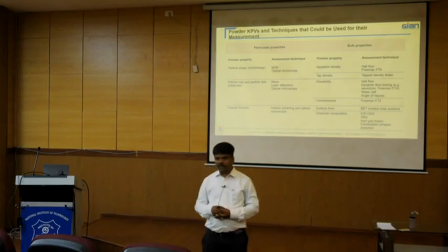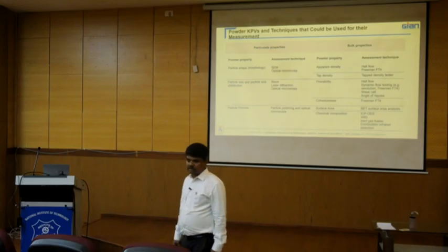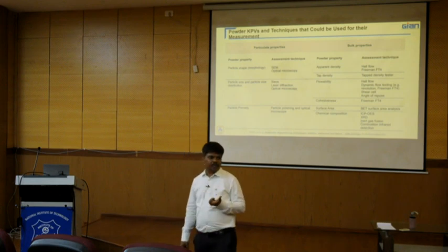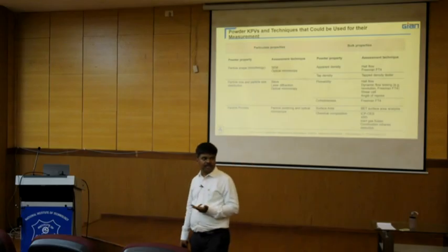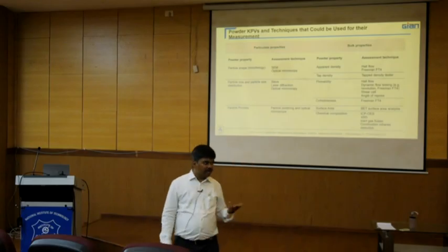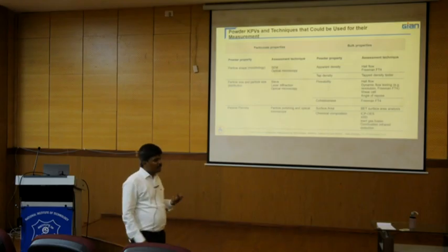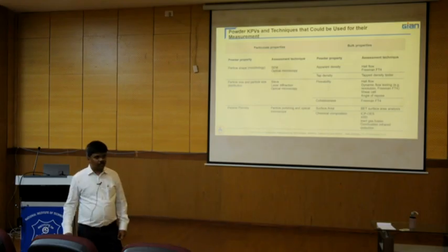Powders are manufactured by water or gas atomization. If powder has porosity, how can we analyze and characterize it? By NDT techniques, or by X-ray CT tomography, or by optical microscopy.